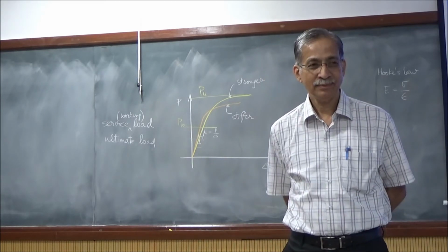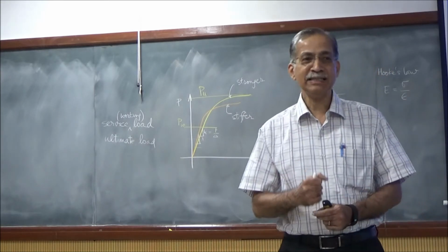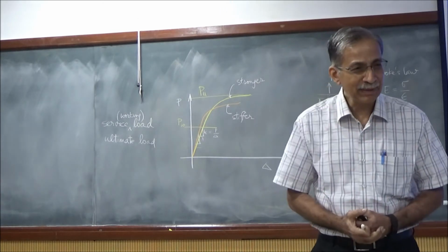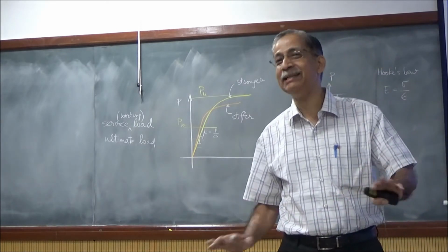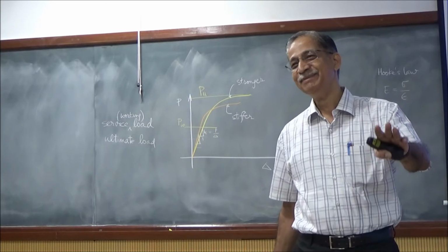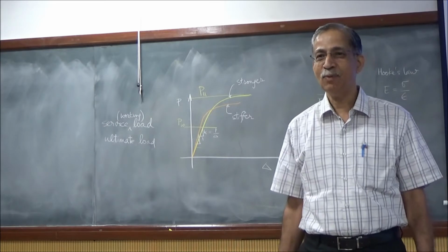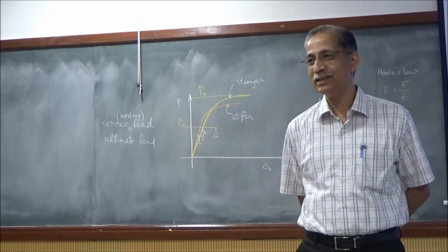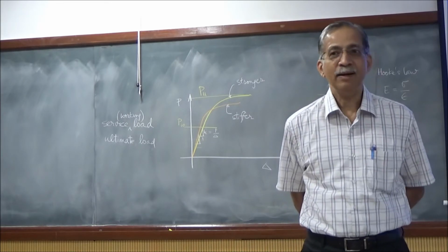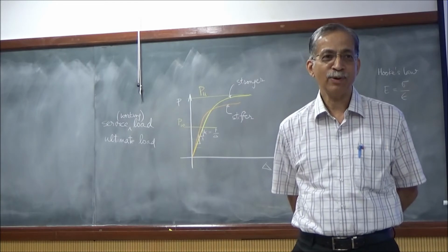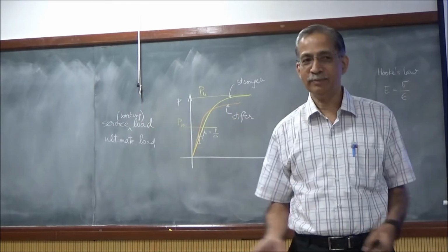Robert Hooke stated that within the elastic limit, the stress is proportional to the strain. Wonderful. So he said for an elastic material, what is an elastic material? Which has nonlinear behavior? No, that's plasticity. Plasticity is another term. Then you've got yielding. What is elasticity? So we are now going back to basics. It is able to regain its shape. Right. The ability to regain the original shape after the removal of the load. That is elastic behavior.